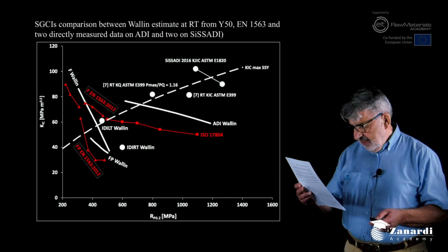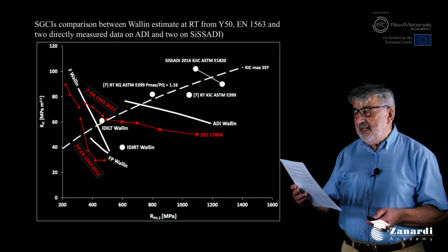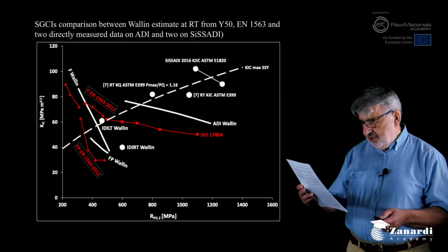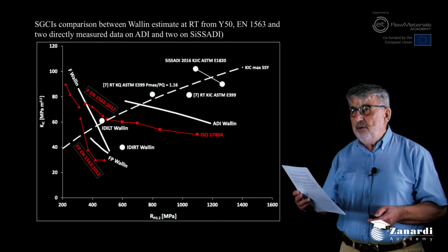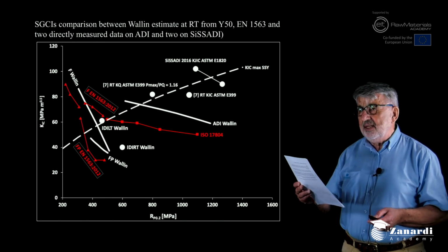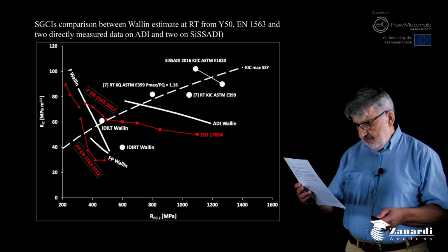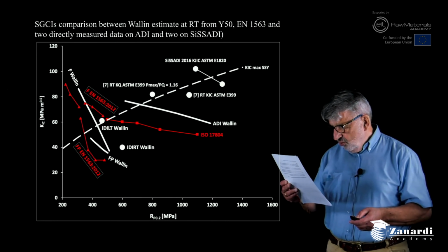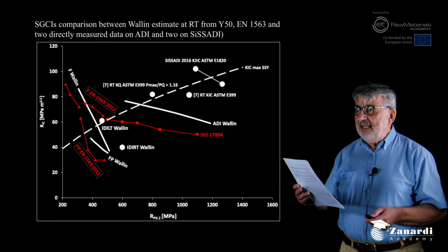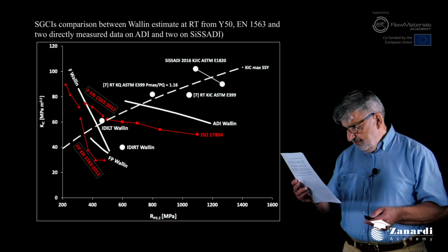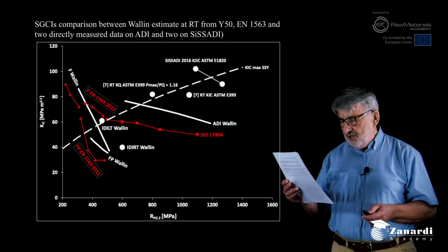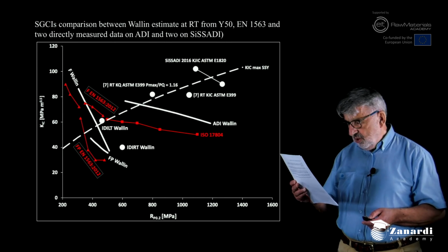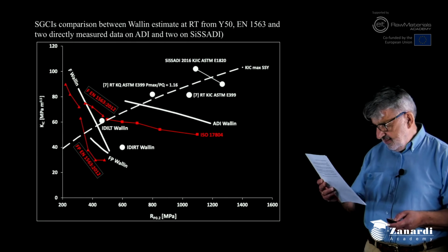In fact, a direct ASTM E399 K1C measurement was not possible using CT specimens up to a B thickness of 45 millimeters, side grooved, and with Rp0.2 799 megapascal, because of a too large ratio of P maximum divided by PQ that was larger than 1.10.